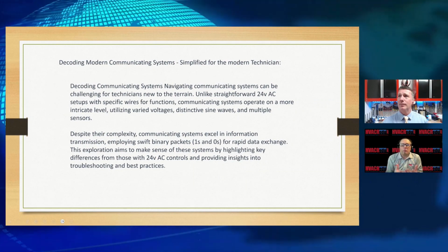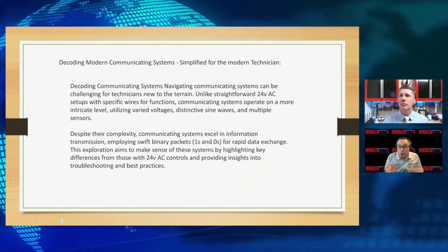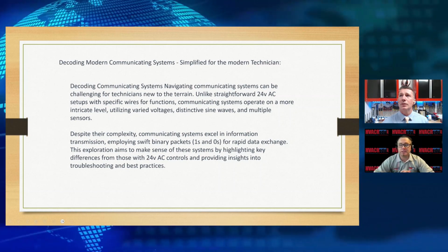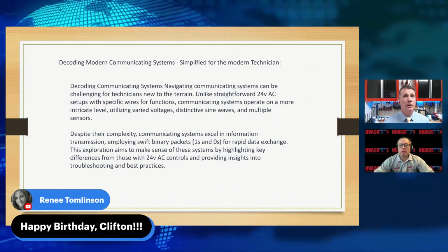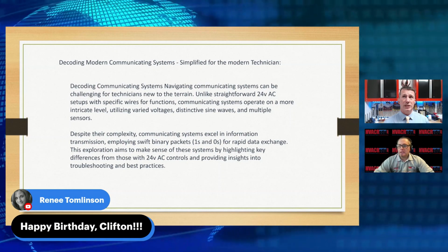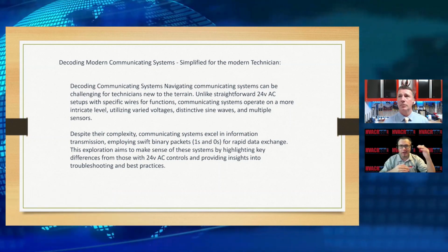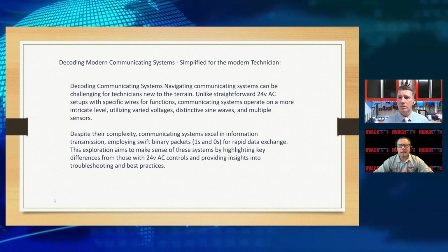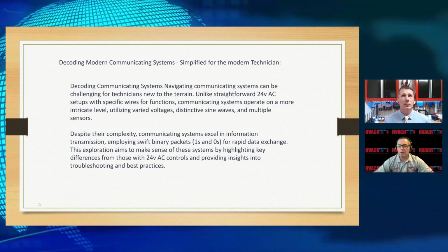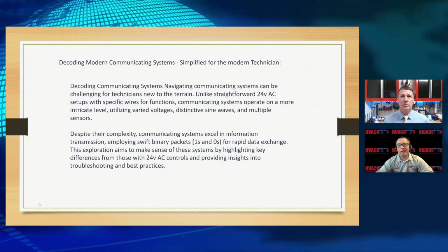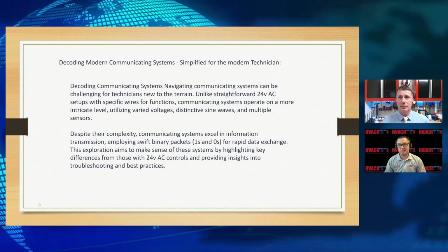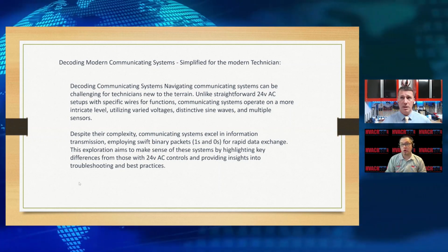Yeah. So most of us, at least in the residential or unitary type split systems, are accustomed to 24 volt, like a switch, and usually that's done. So I'm going to kind of combine this slide and the next slide, I believe they kind of overlap here, but it's our thermostat. In a 24 volt system, we have a thermostat. In a communicating system, it's no longer a thermostat; it's now a network control or controller.